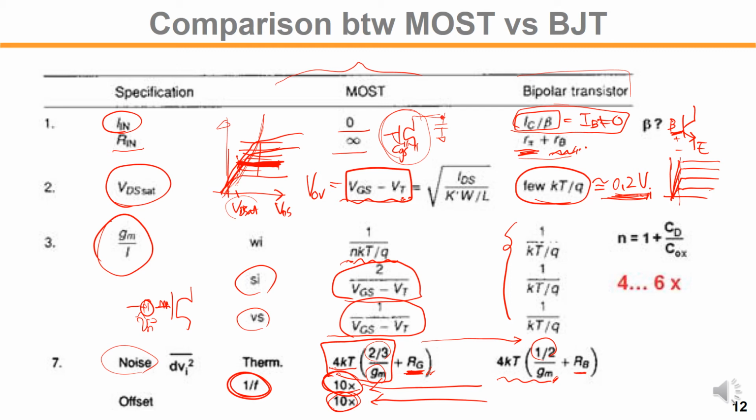So once the voltage on the output is settled, then no more current is flowing. There's no DC current onto the gate. But for the bipolar, there's non-zero DC current. So there's a finite DC current that also needs to flow all the time. That's kind of a limitation.